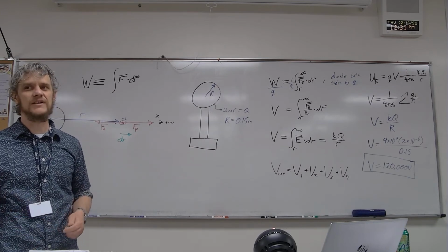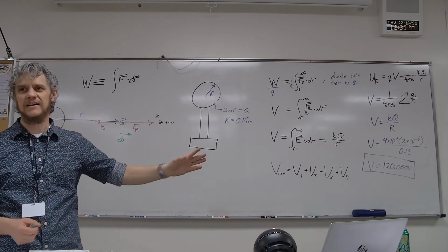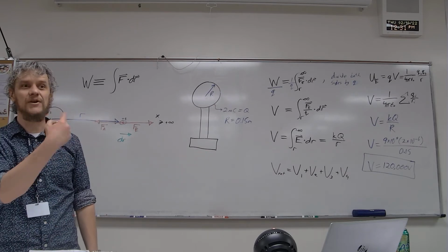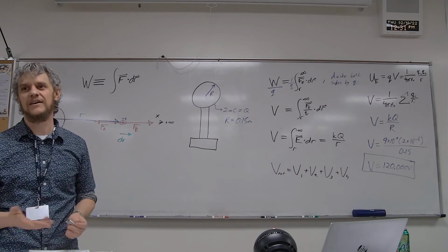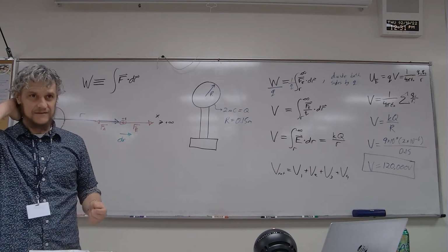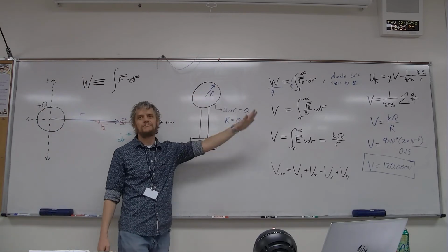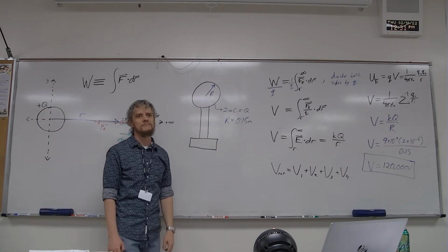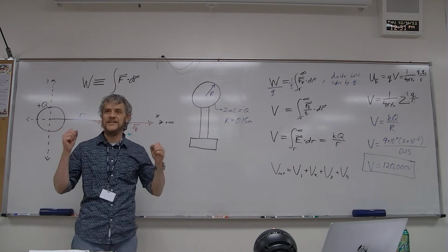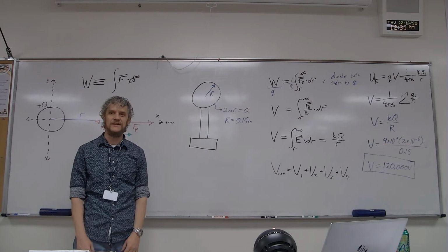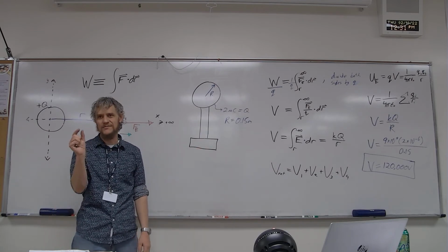So you can have a really strong pump, like the outlet there, and 0 current because it's not actually pumping anything. But if you give it a pathway to pump something, then it's going to pump something. And that pathway could be you, if you're not careful. Same thing with this: if you store charge on it, it has the ability to pump charge off of it, and it has a great ability to. But there's not a lot of charge. So when it does pump all the charge off of it, it's just a little spark. It's fully discharged, and all it was was a little tiny spark.